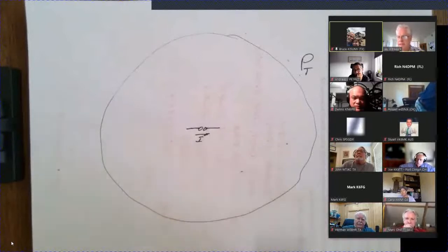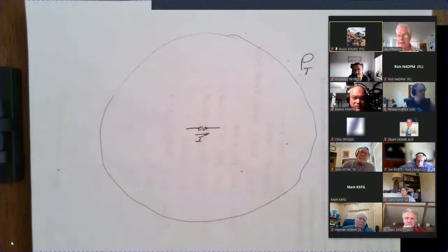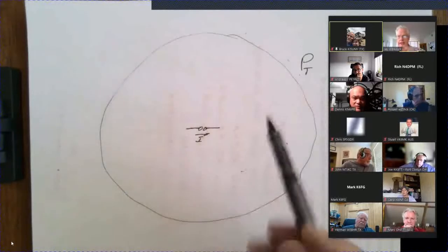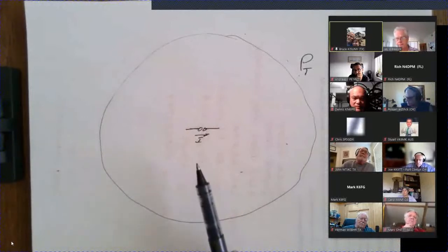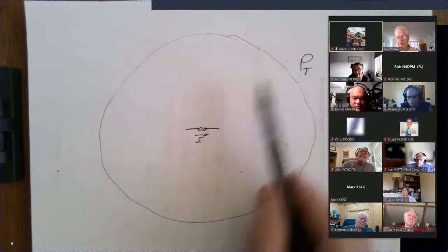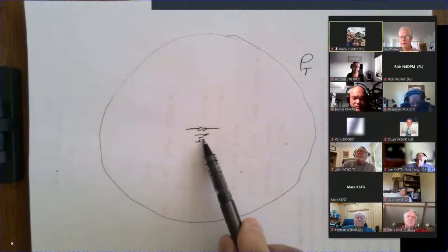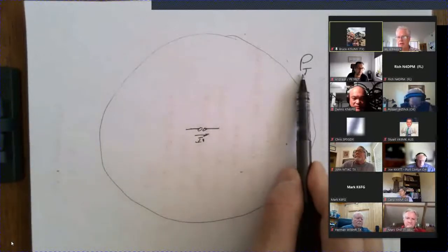So what does this remind us of? It's a resistor. I'm putting current into two terminals. If I had these two terminals in a box and I put a 7 megahertz signal in there, a certain amount of current, and I ran outside and I had this magical device that would measure all the power crossing this giant sphere that's 10 miles across, there would be a relationship here. I have a certain amount of current going in here, and I have a certain amount of power leaving.